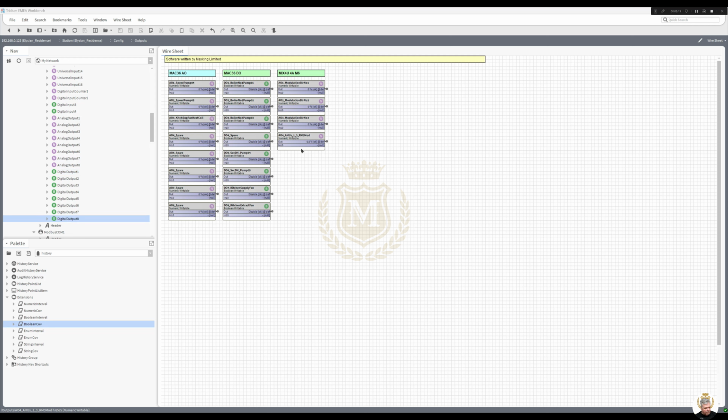Right, what I'm going to do with this as well, these outputs, if we lose the controller completely, network's broken or whatever, I want some of these outputs to be on. At the moment it will all control. If I put an enable in there, it will enable. But if I've lost network, I want boiler pump 1, 2 and 3 to run. And I want these to be at least 50%, so we can run them. And I want the modulations of the boilers to be about 50%, and I want that to be 10 volts to just enable all three AHUs if we've got no communication.